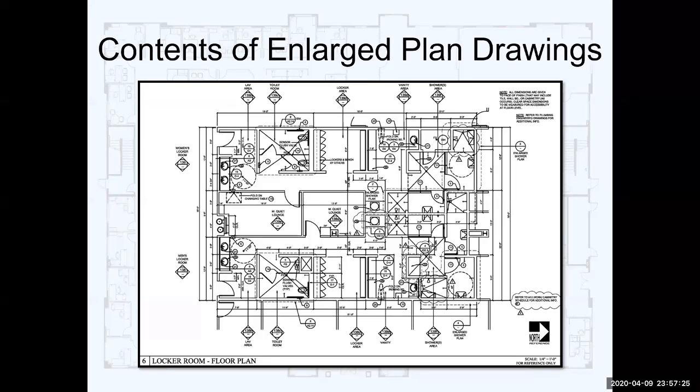Now, you may observe some of these references here. These are clouds. Clouds are what we provide contractors when we make a change to information, whether the client has requested it or whether the building department or inspector has requested it. These drawings get updated to include clouding. And when we cloud information, it's a way for the contractor to quickly go to that information and say, oh, that changed, I need to make a note of it. So these drawings have a kind of a dynamic aspect to them.